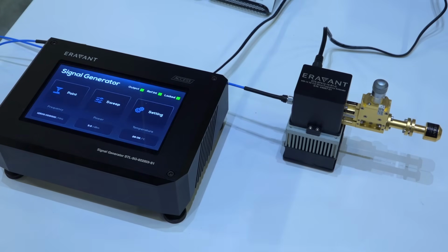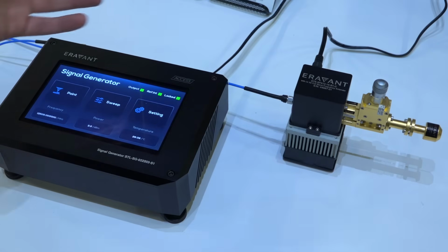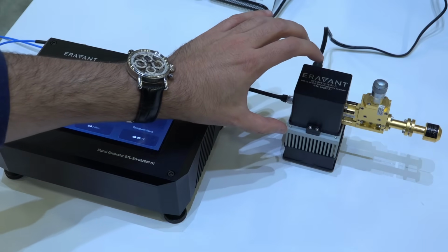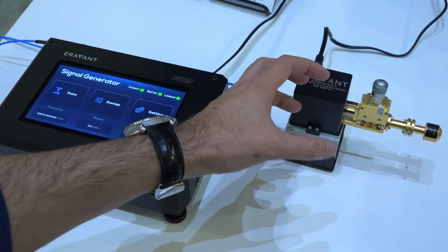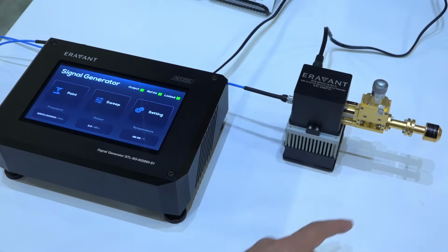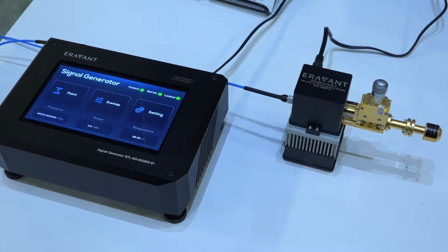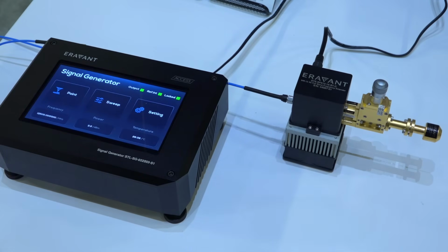So here at Eravant, there's always something new and some new modification to their existing lineup. This is a standalone 22 gigahertz synthesizer box, with a nice display over here. The compactness of this allows you to combine it with some of their multipliers. So here they have an E-band, a 60 to 90 gigahertz multiplier. Very, very small form factor with the USB-C connections on the side that has all the calibration coefficients built in. So you can extract them and find out what exactly the output power is at the measurement plane. This one is also equipped with an isolator, attenuator, a transition, and a waveguide antenna over here, making a complete, super compact E-band signal generator, with reasonably good output power.